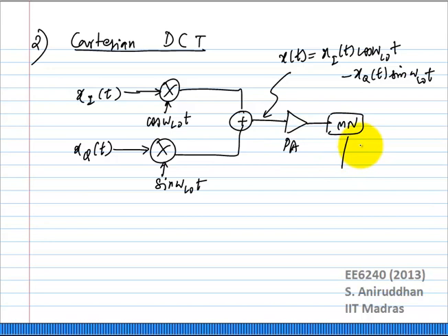What else do I need after the matching network? Now depending on what kind of transmitter I have or what kind of transceiver I have, the output of this power amplifier, which is driving a matching network, could go to two kinds of systems. If you have a time division duplexing system, you need a transmit receive switch to multiplex between the TX and the RX.